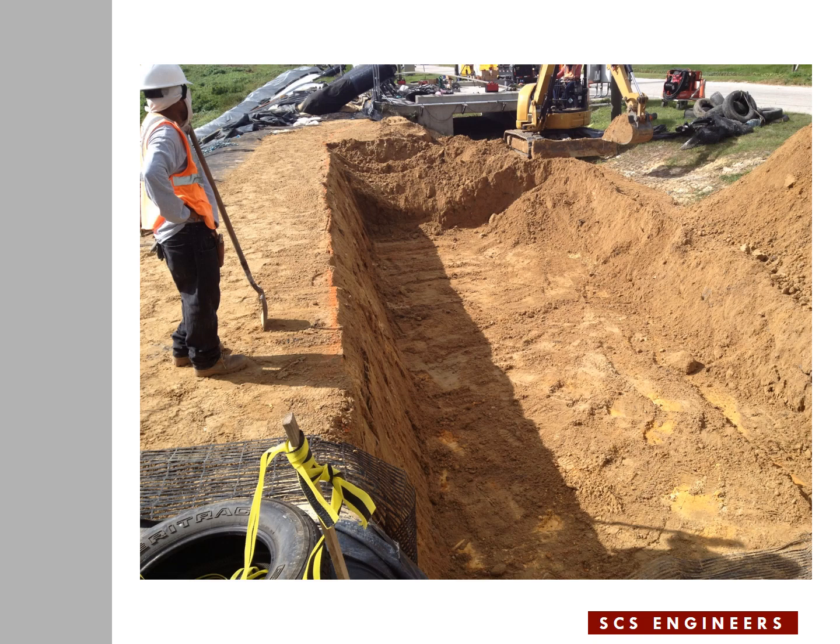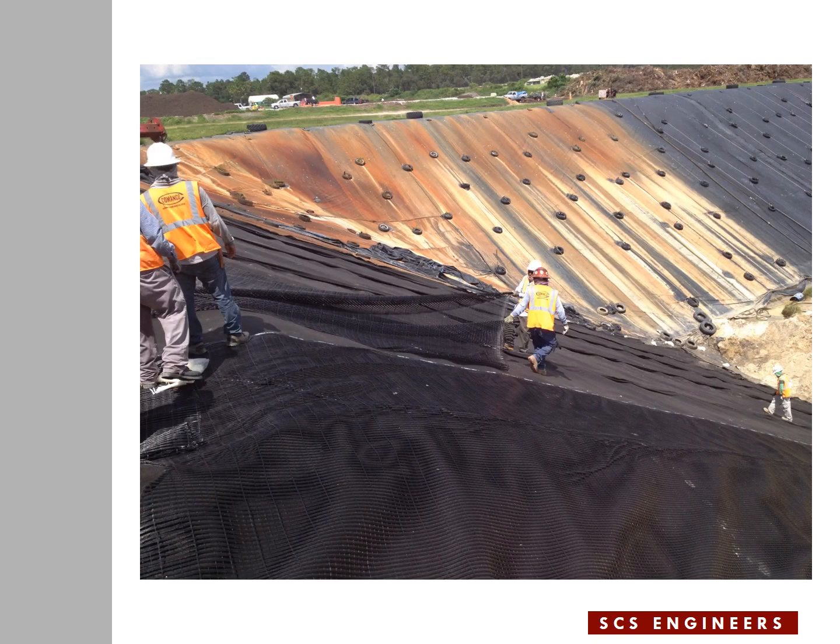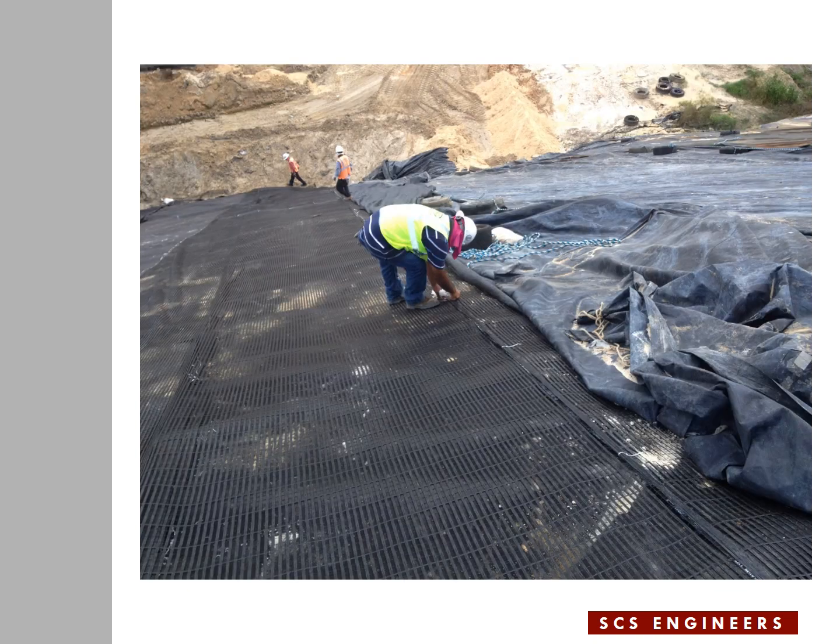This is the larger anchor trench that's being excavated. The previous anchor trench is right at the edge of the geosynthetics to the left side of the slide, almost where the guy is standing with the shovel, is the old anchor trench. After the anchor trench is formed, they start installing the second geogrid, which is directly on top of the geocomposite. The geogrid panels get tied together using plastic ties.